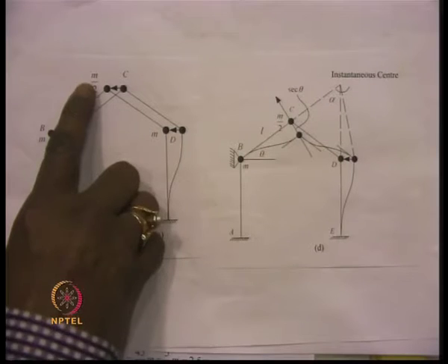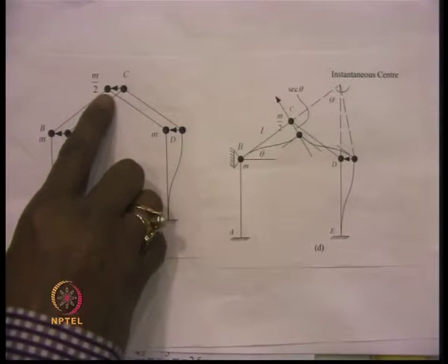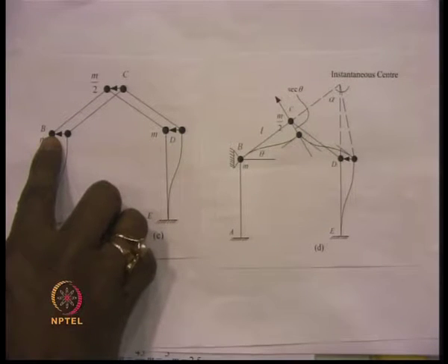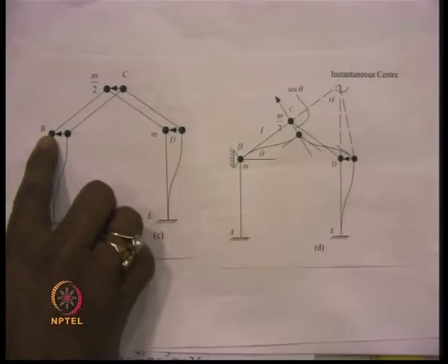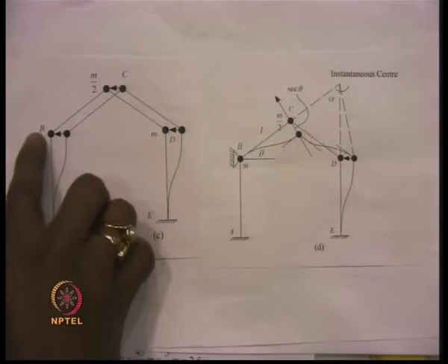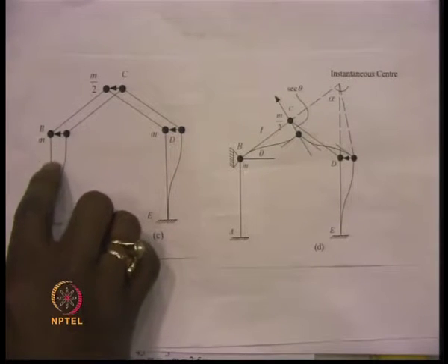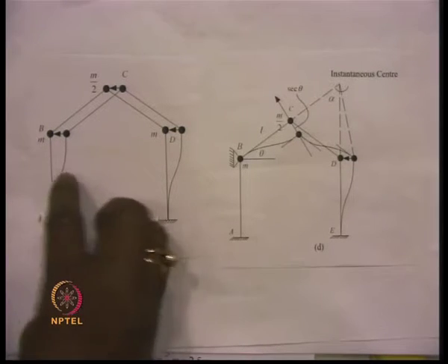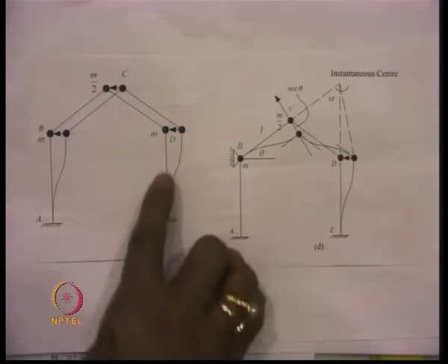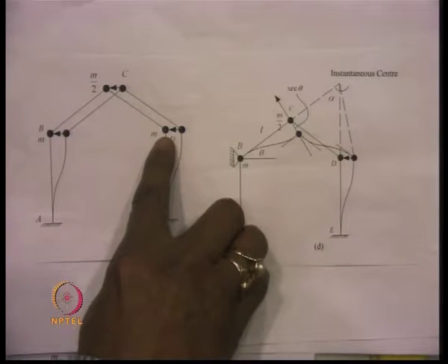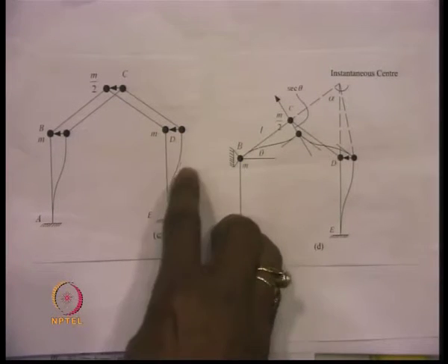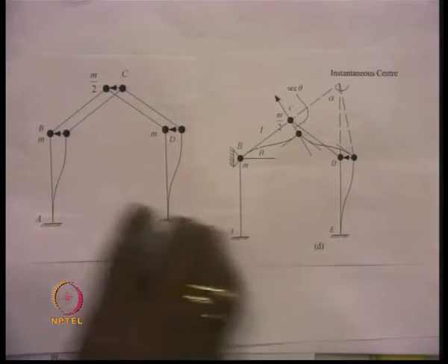The components of these two forces acting along this member are finally transferred to this point, and at this point again we resolve those two forces, one in the horizontal direction, other in the vertical direction. The forces resolved in the vertical direction pass through the column to the support. Here also the force which was existing in the vertical direction, because of the resolution of this force, is also passed to the support.